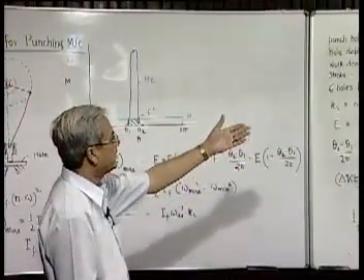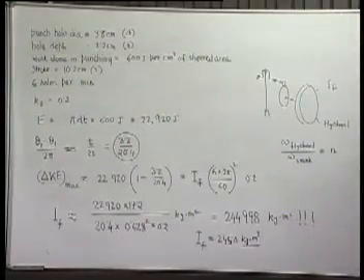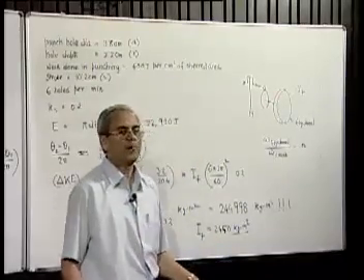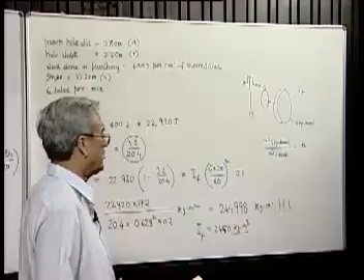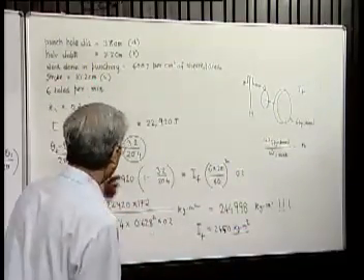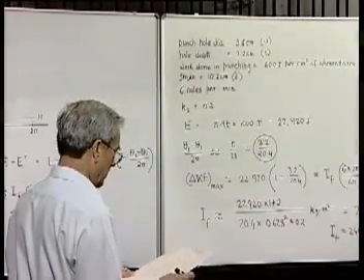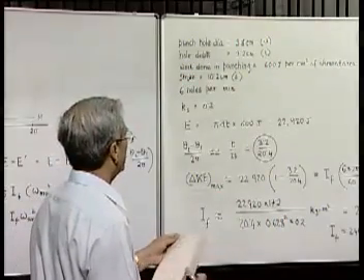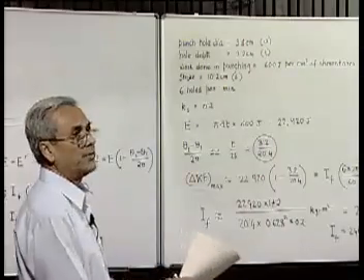If you make the speed a little bit higher, say if you want to make it a ratio of 20, then the whole thing will be still half. It will be only 1.2 ton of a rim, which is quite possible for a flywheel, at a radius of a meter. So this is what I wanted to demonstrate, that connecting the flywheel directly on the operational shaft makes the requirement of the moment of inertia of the flywheel very heavy.